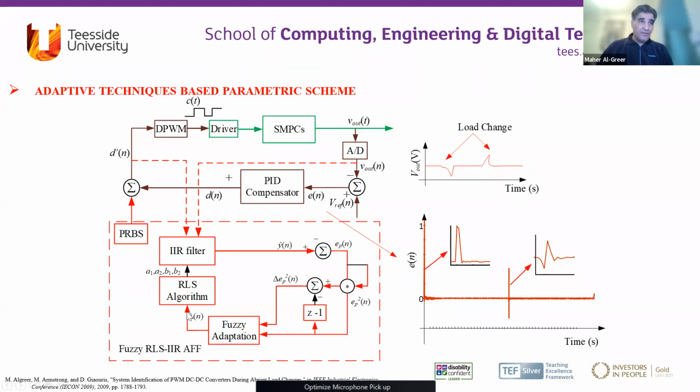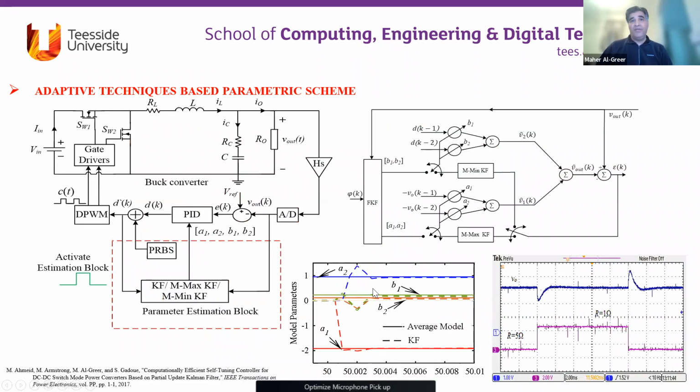The forgetting factor is a very important parameter in recursive least squares techniques, because the convergence time depends on it. A high value will increase the convergence rate, a low value will decrease the convergence rate, but will produce a more robust estimation or less chattering signals, if you like. So we generate a rule-based technique based on the error signals, or the difference of prediction error signals from the AR filter, to track the value or find the optimum value of the forgetting factor, to track these changes in the system when they happen during the estimation.